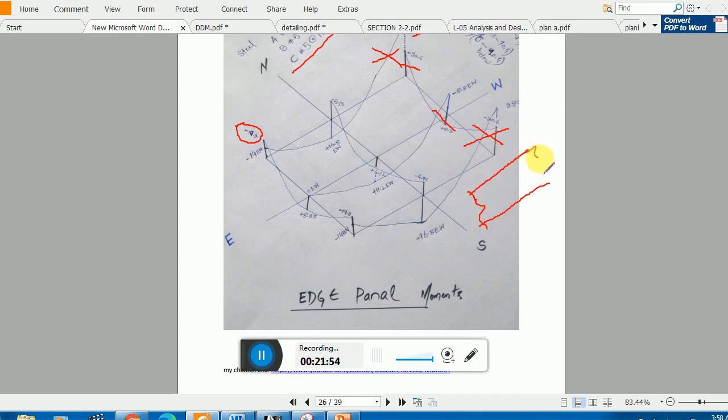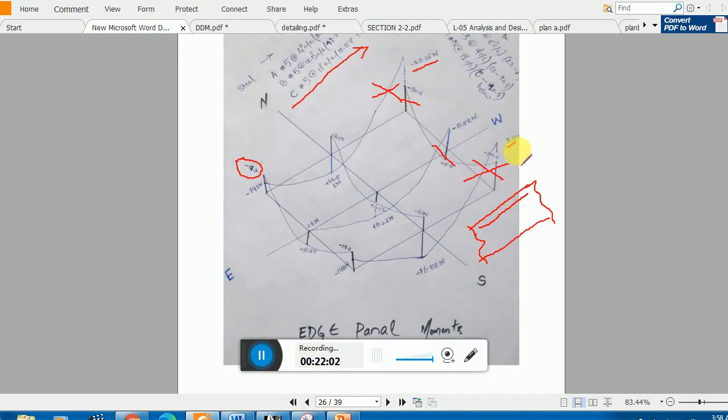Okay, let's say this is my continued slab, and to that side it is also continued. So to cover 28 movement, I have to place the bar in longitude in the top portion. Okay, remember this is opposite, the placing of bar basically opposite as the traditional way we did the slab reinforcement, that the shorter bar should be in bottom layer while the longer bar should be in top layer. Okay, you already know that, but that is the case for beam slab supported.